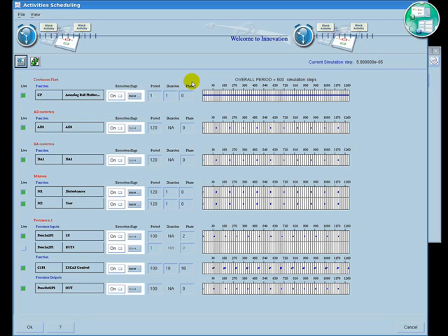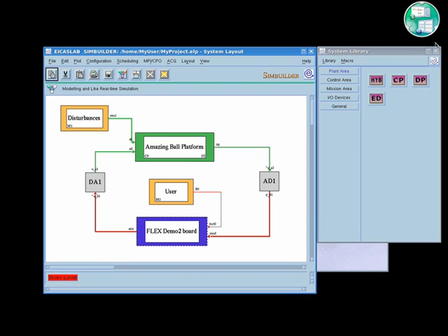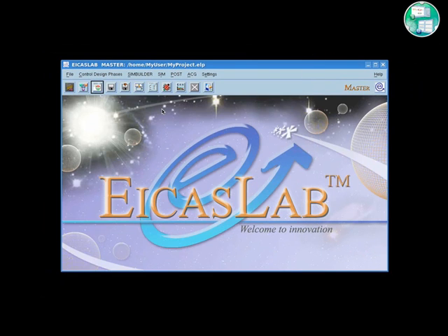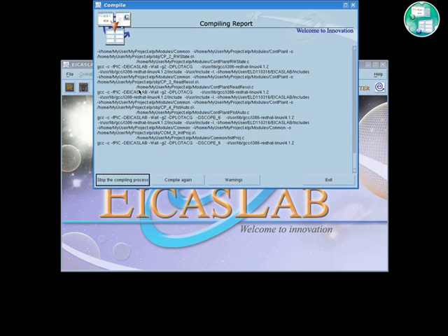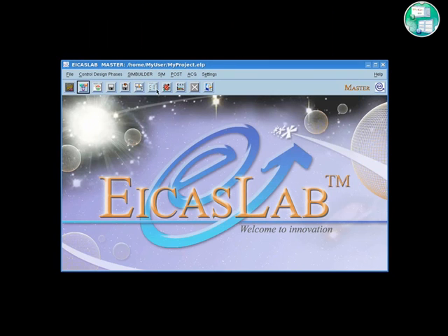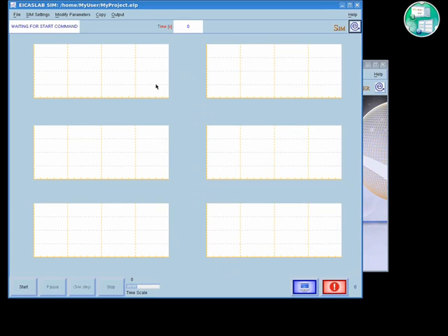Once finished modeling the system, it is possible to start the like real-time simulation phase. Through the master tool, we compile all the code and we launch the sim tool, specifically devoted to managing the overall simulation phase. On the bottom of the sim graphical user interface, a control panel is available, including a button bar for starting, stopping, and time scaling the running simulation. It is important to underline that the timescale option acts in interaction with the like real-time scheduler, always guaranteeing the correctness of the simulation.